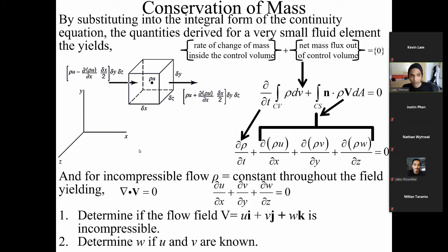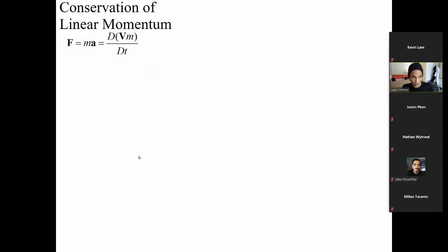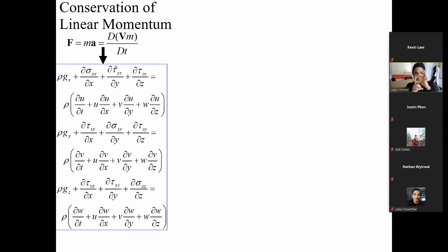Then from there, we moved on to the linear momentum equation, and we said, hey, we're going to start with F equals ma. And we're simply going to write this side right here in the following way, which was the acceleration term, total acceleration that we dealt with before. And we simply brought the m inside the parentheses. And then from there, we went ahead and for the small fluid packet, we solved for the 3 components of the linear momentum equation, which is this really big equation.